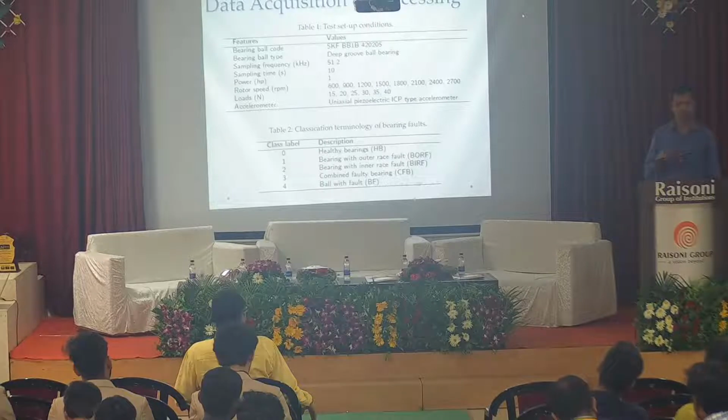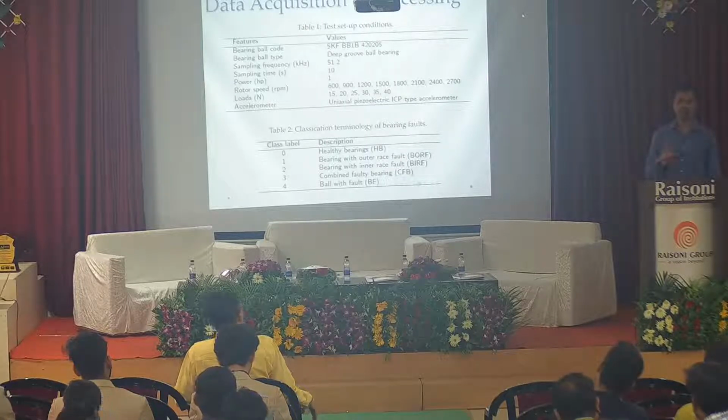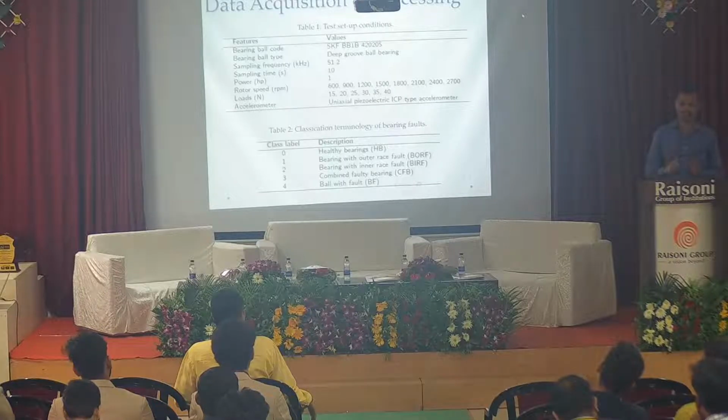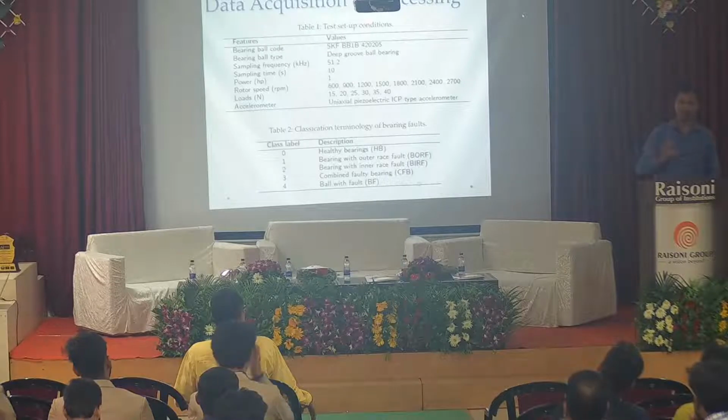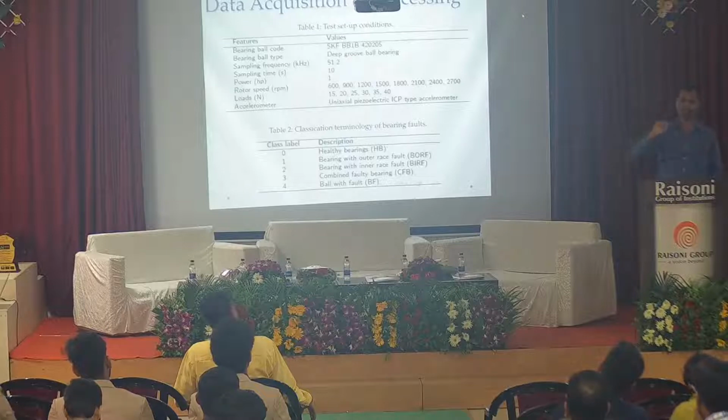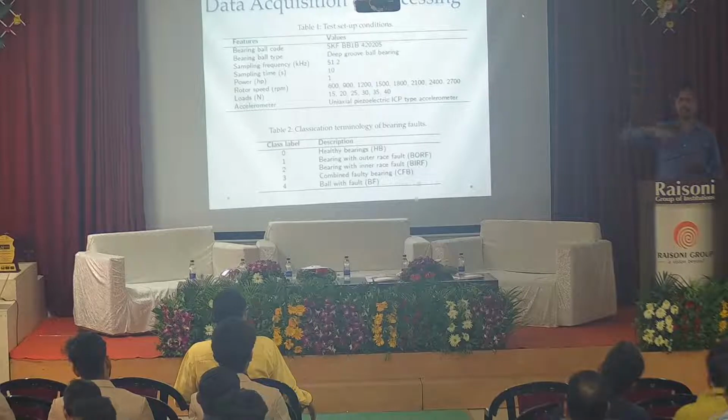But if you are monitoring some machine or some nuclear plant, you have to collect the data continuously. So why am I talking about how frequently you should collect the data? Just think, you deploy a sensor in a particular location, and it will throw the data on a network. If you throw the data continuously on a network, network congestion can occur. And not only that, our database will have a significant amount of data. So depending on the type of application, we have to decide our sampling frequency, and then collect our data.